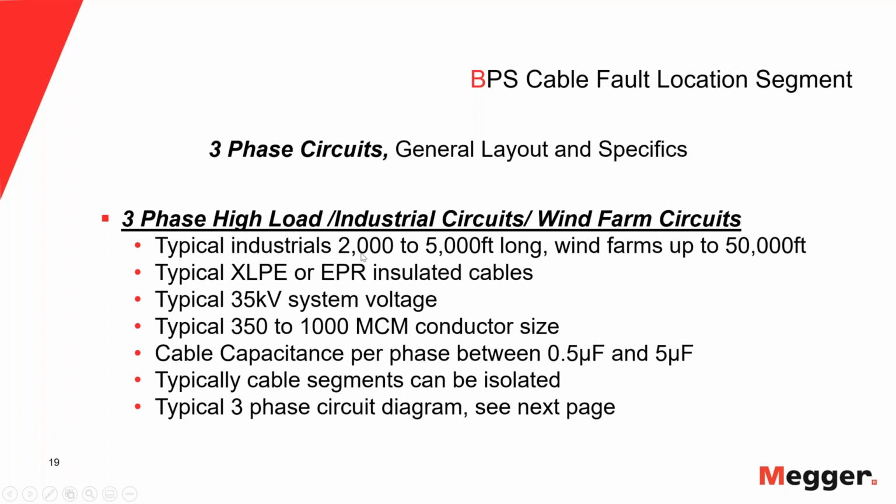Most of the time in these types of circuits, the cable segments can be isolated, and that is very important, because when I have isolated segments of cable, my fault locating procedure becomes a whole lot easier compared to when I have one piece of cable that is, like we had in one particular incident with one wind farm, 26 kilometers long. Then fault locating becomes very difficult.